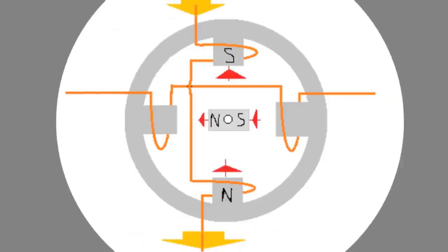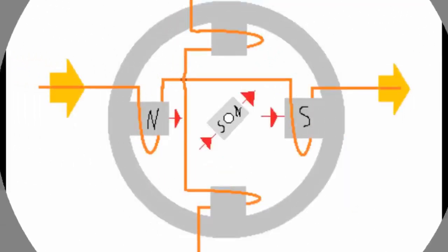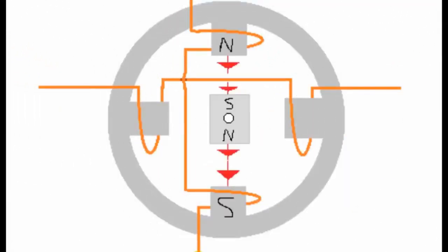So how does a motor work then? We place a magnet, the rotor, into this magnetic field, and it sort of latches onto the magnetic field with its opposite poles and starts rotating at the same speed as the field. And that's how we get a synchronous motor.